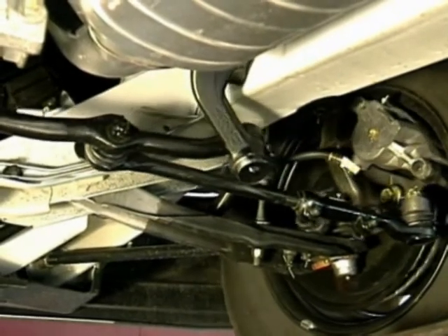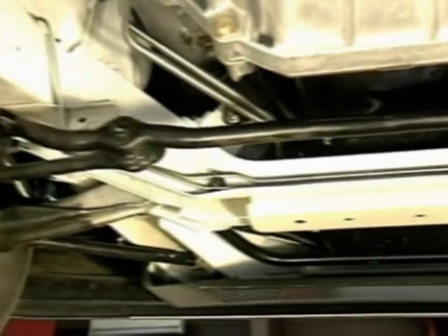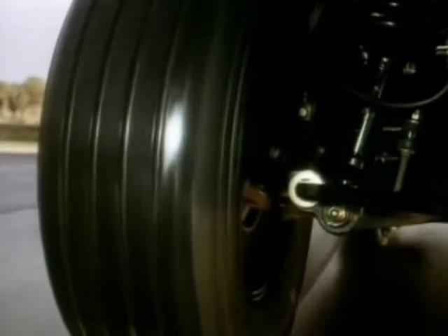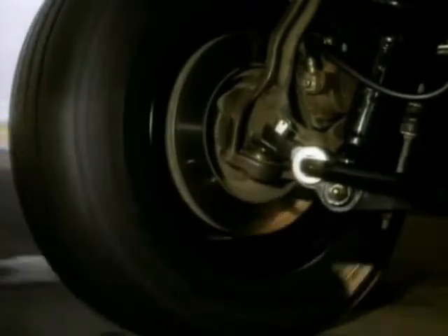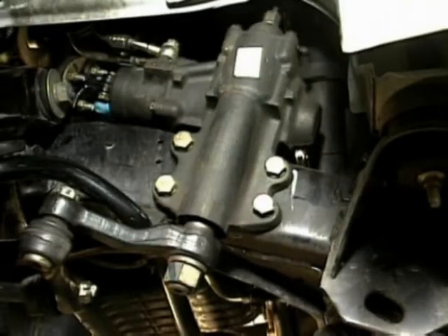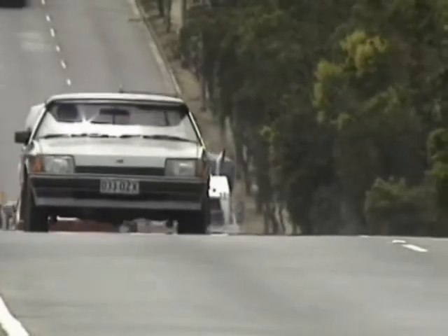The steering linkage is a combination of rods and arms that transmit the movement of the steering gear to the front wheels. It must transmit this movement to the front wheels while still allowing for up and down movement they may make while the vehicle is in motion. The type of steering mechanism and the number of linkages depends on the type of steering box, its location, and the type of suspension on the vehicle.